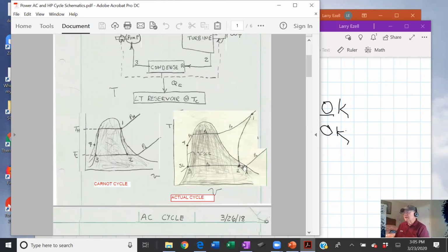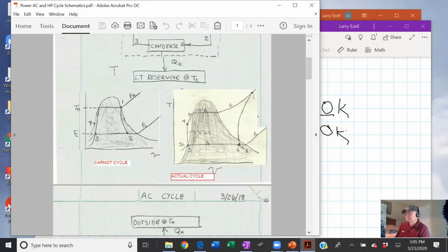Well, I take that back. I think I said it's really at high temperature. It's really pretty low temperature, isn't it? So I guess I was wrong about that. But there's still a lot of energy in the fluid. So, okay, low temperature, low pressure. And by the way, this low pressure is typically a bar or less, say a half a bar. So we're going from, what did I say, 200 bar down to less than a half a bar through the turbine. A lot of pressure drop, isn't it? Get a lot of energy out of it.